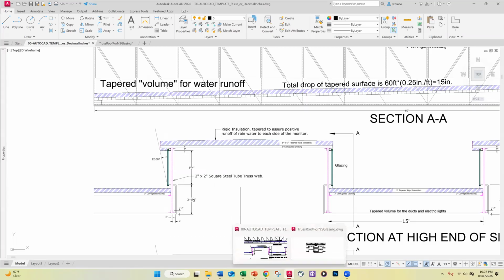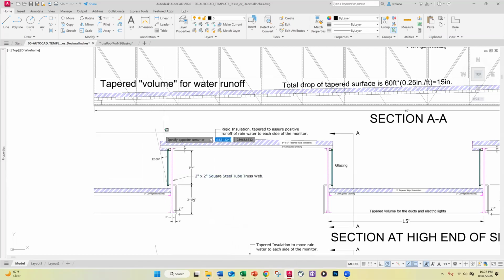Typically, this is more like 15 or 16 to 20 degrees if we only have south-facing apertures. But because the south apertures are only half of the glazing, we're not going to get severe thermal overloading, so we're not putting out quite as big an overhang on the south side.